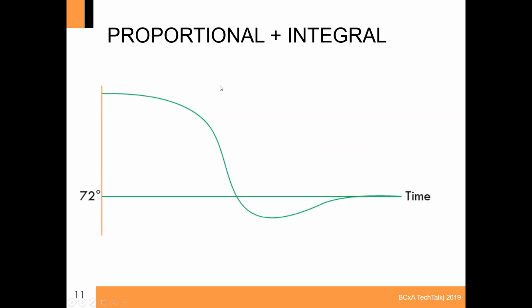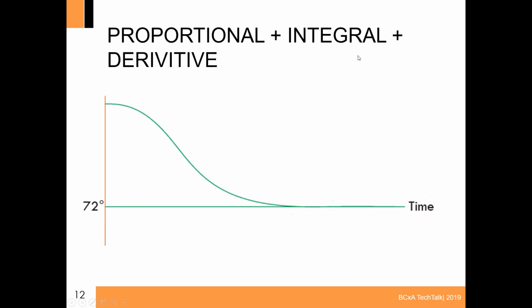That's where you get to proportional plus integral control. Now, integration, the area under the curve in mathematics: the algorithm not only has a proportional output, but it's also looking at whether there's a positive or a negative area under the set point over time, times the x-axis. And it will increase the output if you're up here or decrease the output if you're down there. This is where you can actually get right on set point, okay? And again, this is what 90% of the loops within direct digital controls use.